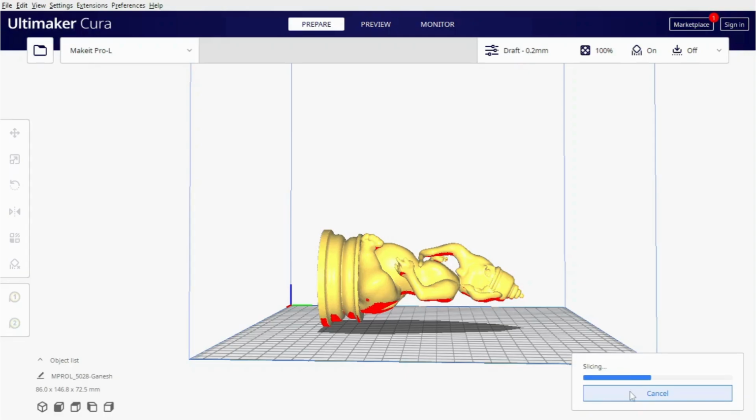Because we are going for layer by layer manufacturing. So that layer thickness is very much essential, right? By this automatic slicing we can adjust that layer, and the machine will suggest what slice thickness you can consider. So different slices will be considered. Here you can see slicing is happening, right? Now you can see the machine has sliced the complete geometry, the complete product. It will show you the time as well, and based upon the machine capacity the time may vary.